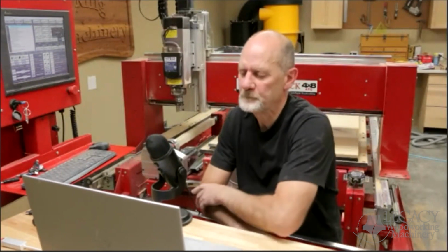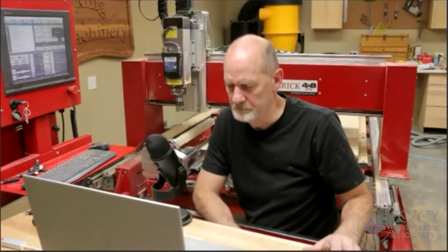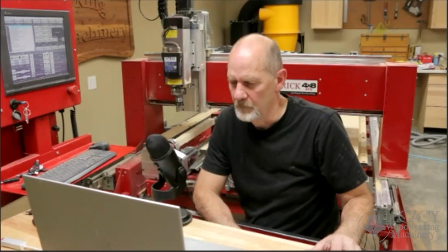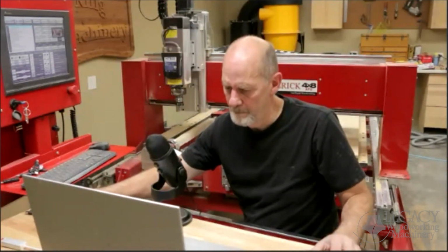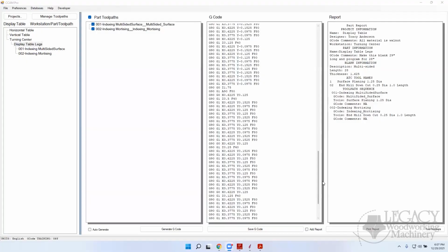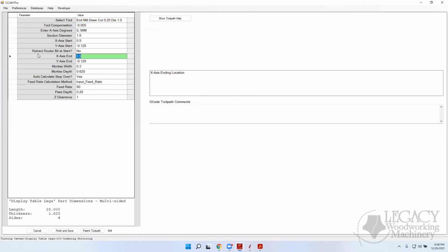Tracy, is there any control on the plunge rate? Let me take a look real quickly. Okay, tool compensation. Feed rate 80 past dip.